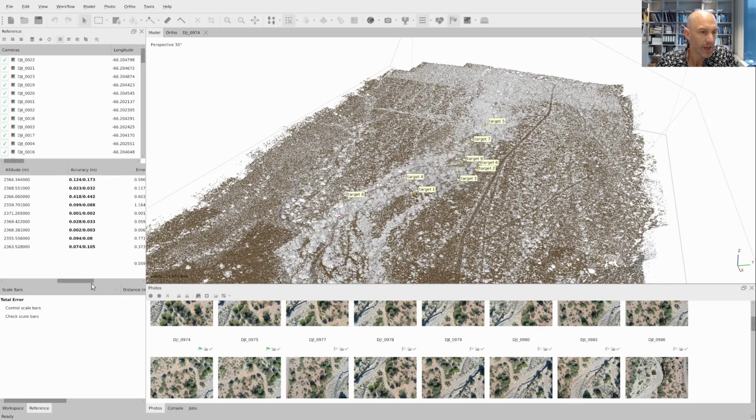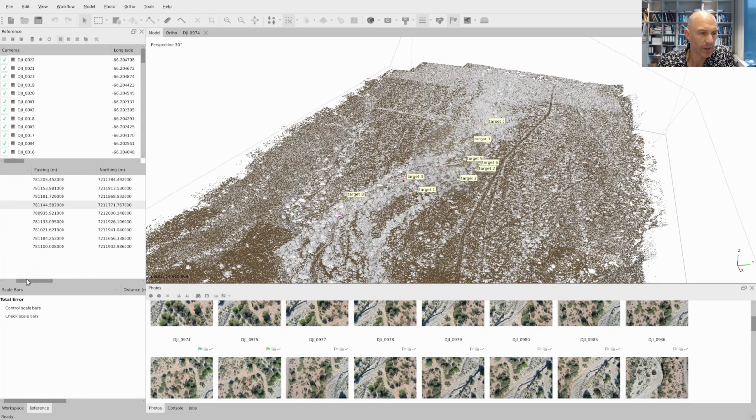Before we wrap it up here, I just wanted to go back to our reference frame and look at the uncertainties, the errors. Currently we are back to about 0.5 meter average error for the targets, which is okay for this large survey site, but you see that there is particularly one site with a larger error. This would be something where we could go back and make sure that the markers that identify this target, target 4, are accurately clicked, and then maybe we can improve upon this, because we have a couple of targets that usually look very, very nice.